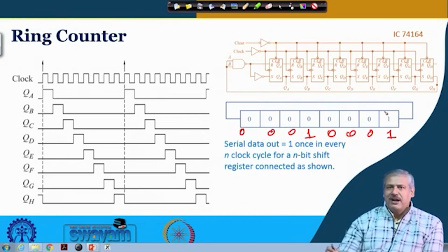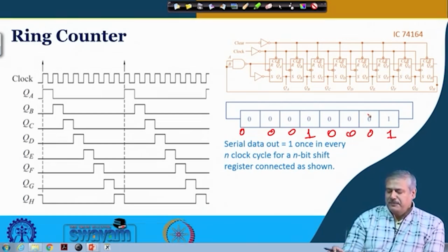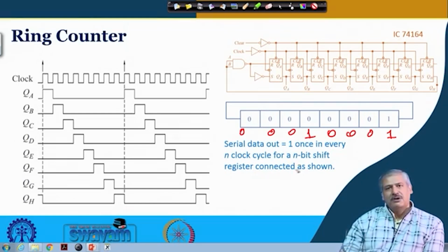But with this ring counter arrangement, if it is an n-bit shift register with as many flip flops, maximum we can get a mod n count. Okay. So, that is what is mentioned. But we can get less, depending on how we are initializing the flip flops, clear.